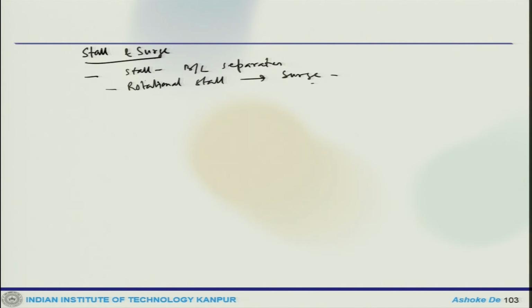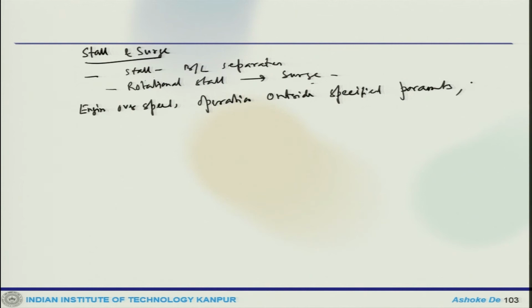So, there are certain things like engine overspeed, operation outside specified parameters, sudden turbulent flow at intake, or some other damage to the performance of the engine. So, these can all lead to stall.